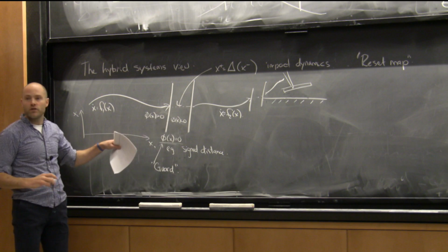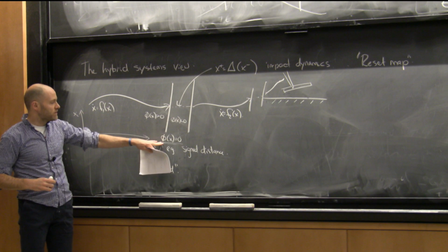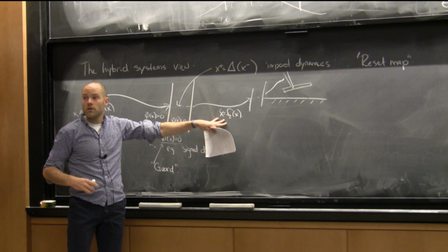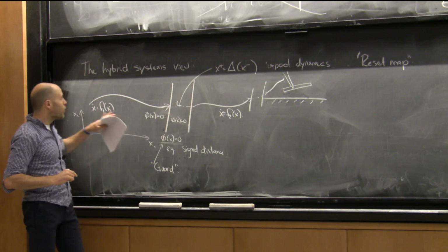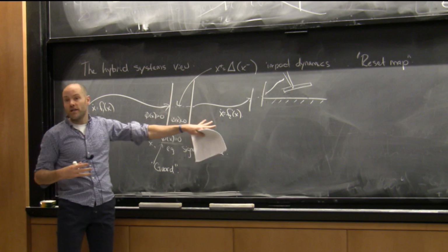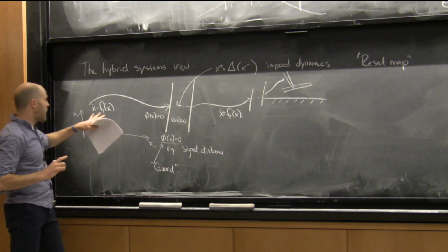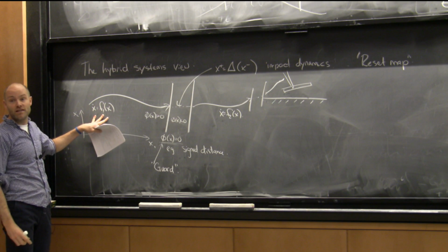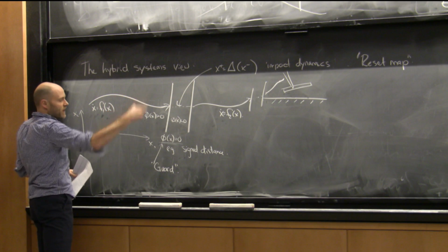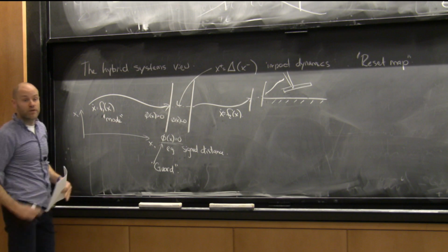So what's the more general way to do trajectory optimization through contact? Well, if I have explicit parameterizations of phi, of F1, of F2, and if I'm willing to decide a priori which modes I'm going to be in and in what order, that's a big one. I have to know that I'm going to have a few points in F1, in mode 1, let's call it. We have guard, reset, and each individual dynamical system is called a mode in the hybrid systems world.